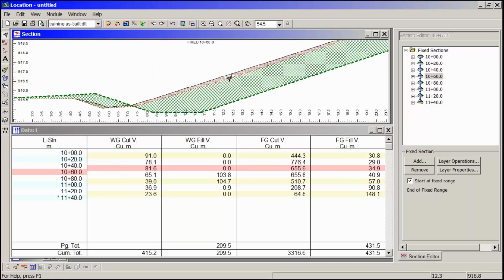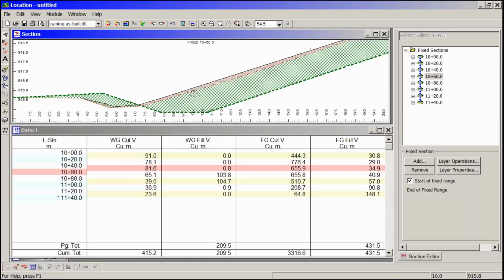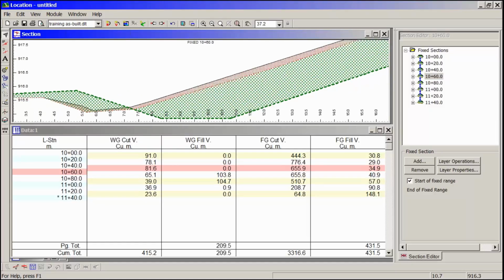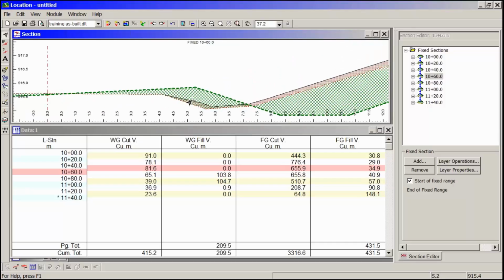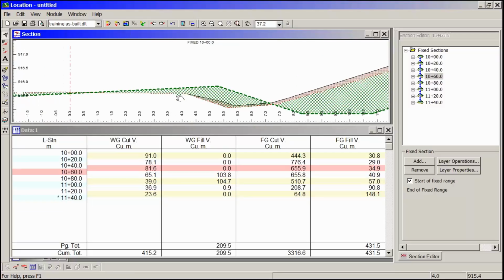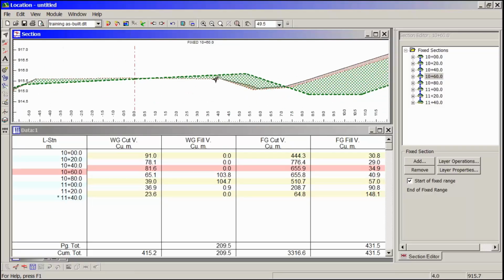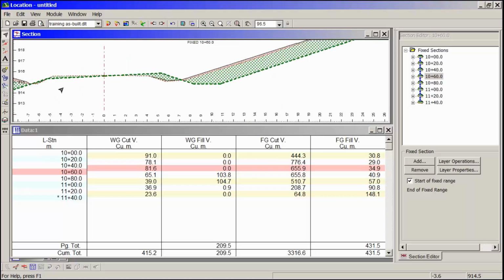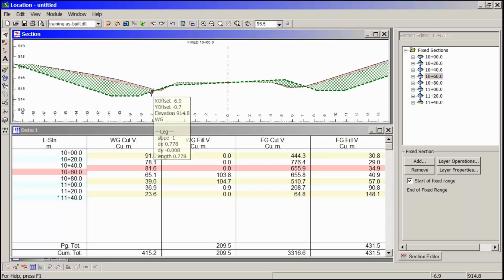The strip surface is just a close dot, a red dot here that you see. Okay, so just a little bit more about how this is surveyed. Obviously, the original ground is surveyed first. The road is designed. Stripping has been taken away. The stripped surface has been built in the field.